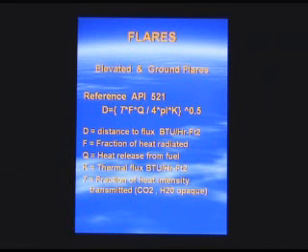The Q value, which is used. Let me back up. The flame fraction is a multiplier on the Q value, so it basically reduces the amount of radiant energy that is given off by a combustion process. So if you have 20,000 BTU per pound of a fuel gas, and you have X number of pounds of fuel, that defines a gross combustion heat release.